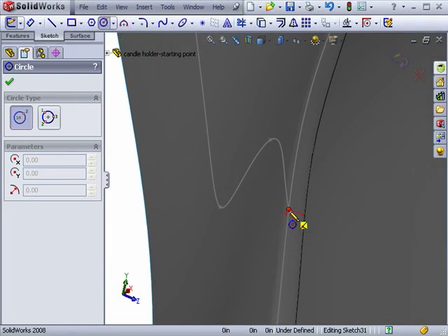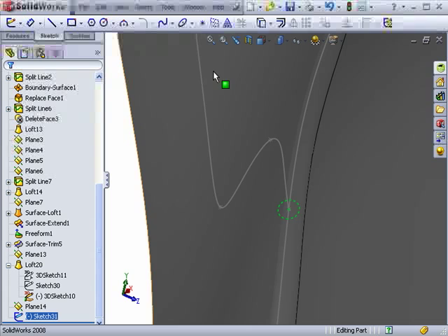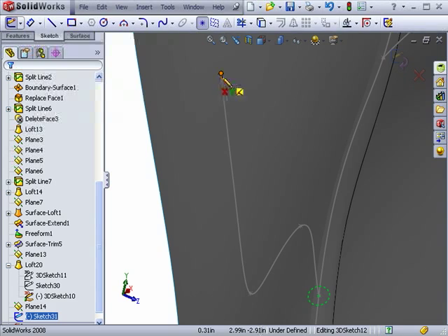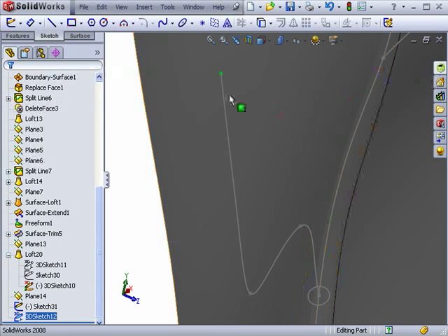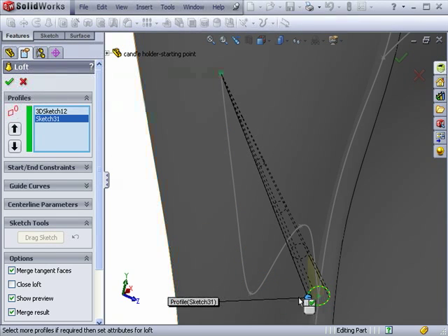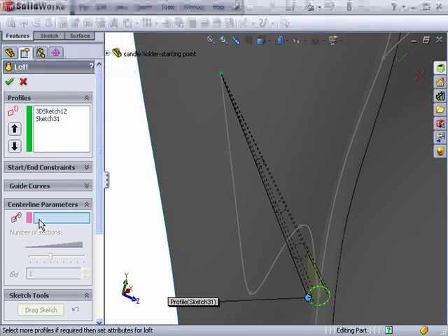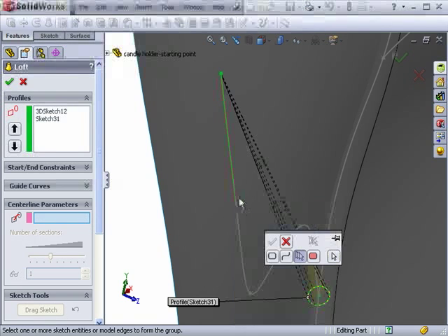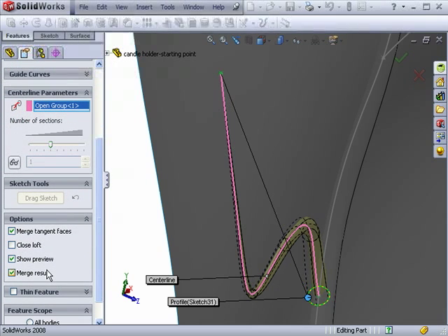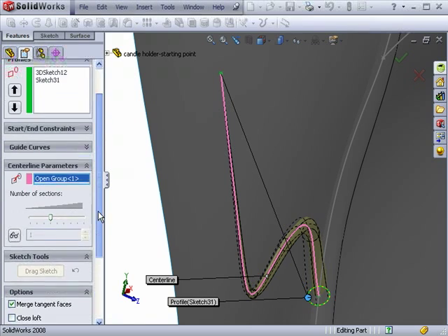In order for the veins to be blended together later, the smaller veins will start with a smaller diameter circle. This will guarantee that their starting point will be completely contained within the larger vein, allowing a fillet to blend them together. Also, although the first vein was purposely not merged with this base, the remaining veins should be merged with the main vein. The end result should be a continuous solid body representing the vein network.